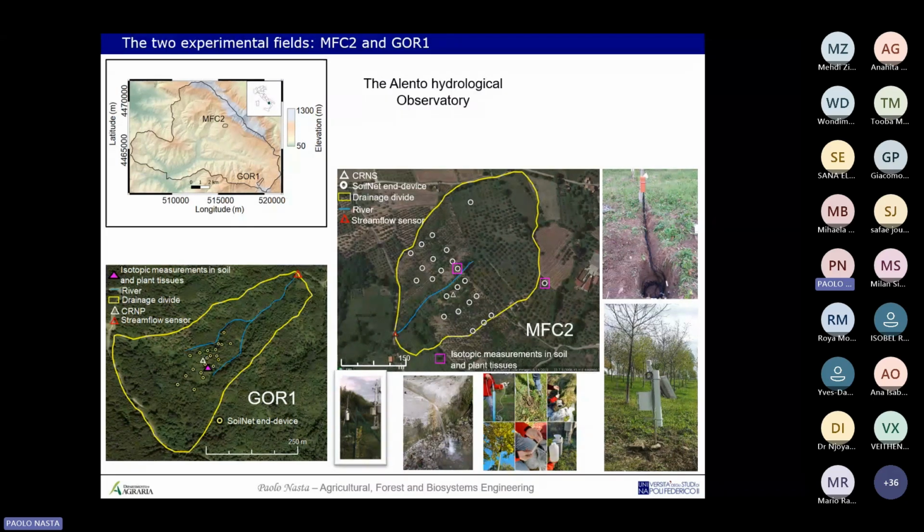And from permittivity, we estimate the soil water content, as Nunzio explained in the first day in the soil water content webinar. We use our own calibration law. We went to the field several times to measure directly the soil water content, and we developed our site-specific calibration equation.